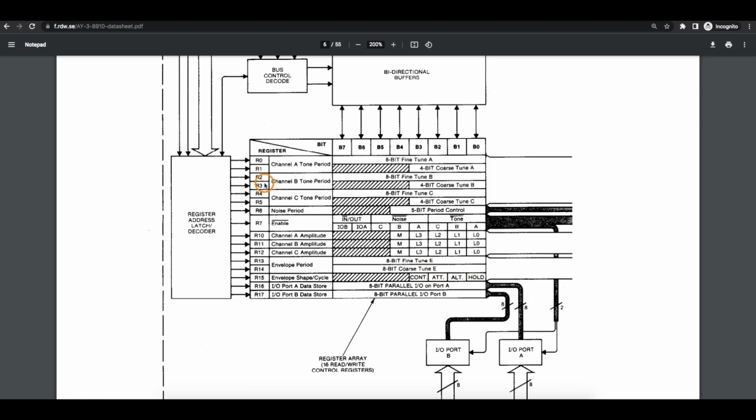So one of the things that confused me with trying to figure out in a Nano, how do I tell this which register I want? We know there's 16 registers. This goes from R0 to R17, and here it skips from R7 to R10. So I realized later, this is in octal as opposed to decimal or hex. So really this goes decimal 0 to 15, but the Arduino library takes care of that anyway, so it's just a weird thing. I'm not used to dealing with octal.